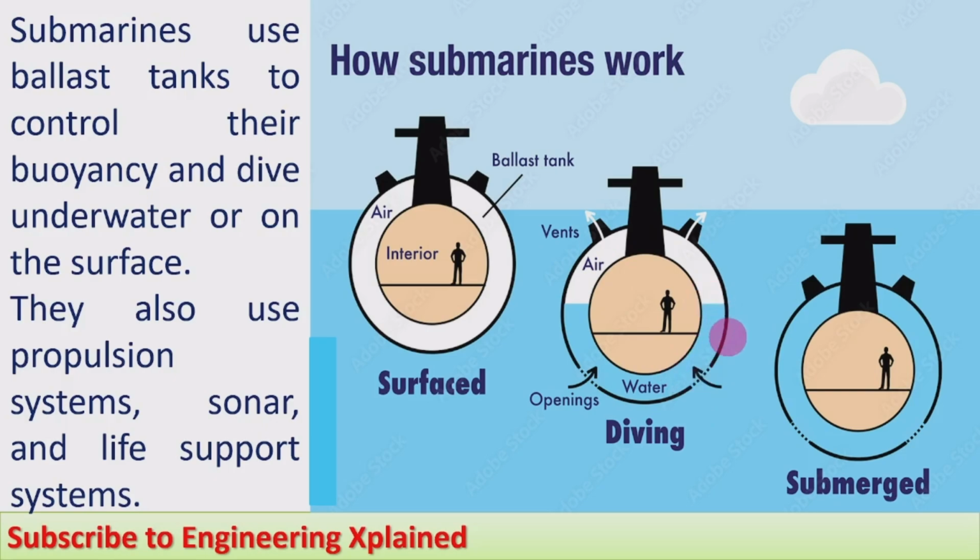That is how it starts diving. When the ballast tank is completely filled with water, it will be submerged inside the water for a particular distance into the sea from the surface, and that will usually be calculated and also maintained during the submarine's travel under the submerged case.